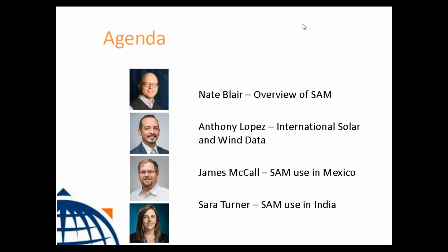This question on an India-specific clear sky model. Does that mean anything? Consider an India-specific clear sky model and the concept of estimate solar radiation. So I believe the model used was a semi-empirical model, the Perez model, for the irradiance calculation in India. And as far as clear sky is concerned, I am vague on the details, but we did have some interesting troubles accurately modeling the aerosols in the beginning, which caused us to do a second release of the Indian solar resource data set. So yes, we did consider local aerosols.